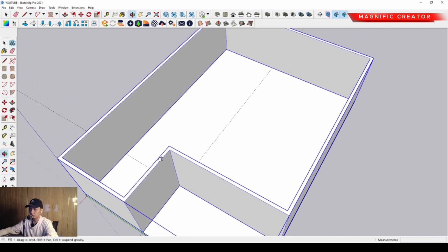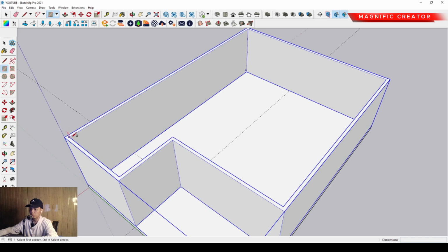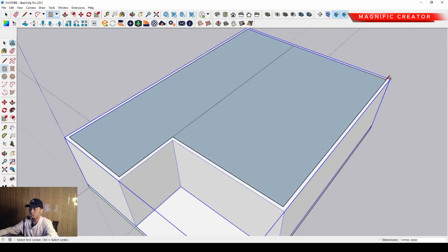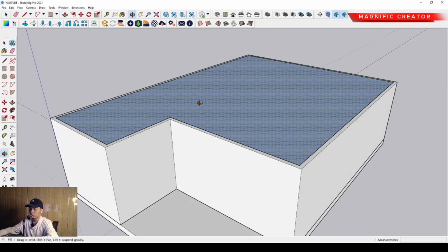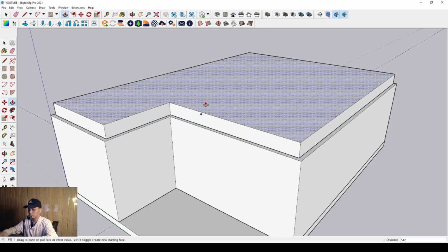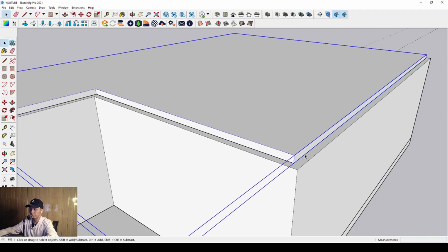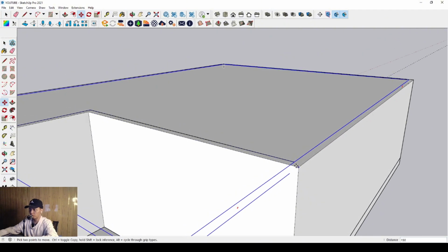After that we can make another slab element over there. We can use a rectangle. Then we can select with shift, then place it on this position. Then place it in this position also, and then we push it up around 150 millimeters for the slab thickness. Then we can make a group, then move it down, something like this.